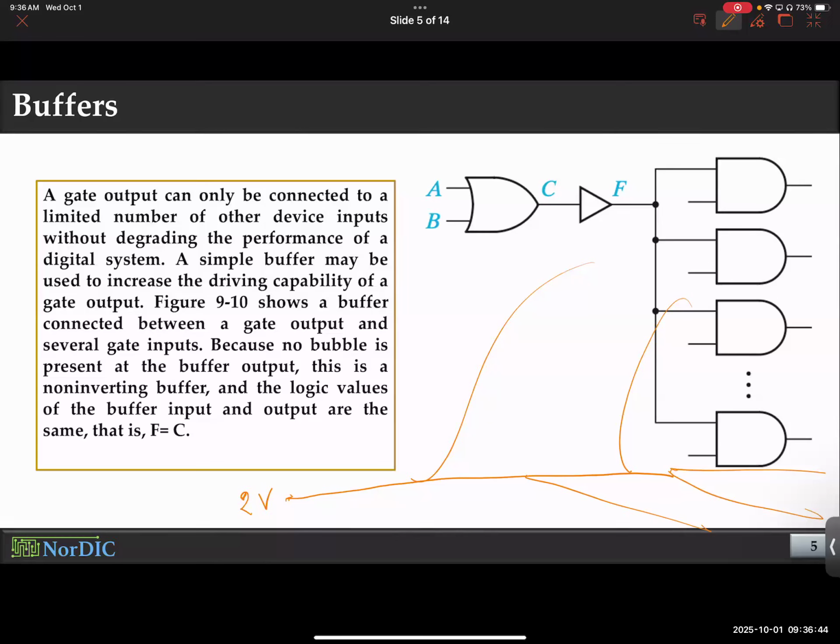You run different components in the circuit with the same voltage, right? Do you think, according to the convention, we understand that all of these nodes will have the exact same voltage? At least that's how the simulator works, because they consider ideal interconnect. But practically, there will always be resistance in the wires. You see that? So because of this resistance, you'll never get full 2 volt in every node.